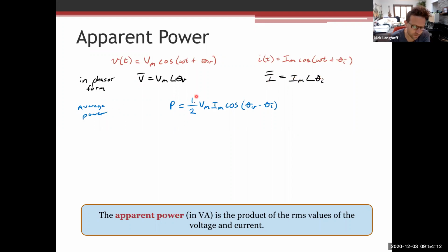The average power we've already shown. Remember, we reviewed this at the beginning of this lesson today, that it's 1/2 the Vmax times Imax, the product of the peak voltage and current, times the cosine of the phase angle, the difference in phase between them. If you're looking at where my hands are, if they're perfectly aligned, they're like this. My right hand is, let's say, voltage, my left hand is current, and as they're phase shifted, they're shifted in time or phase angle, and we measure that in degrees, as we've discussed. Remember, this is that DC, or average, part that we pulled out from the instantaneous power.